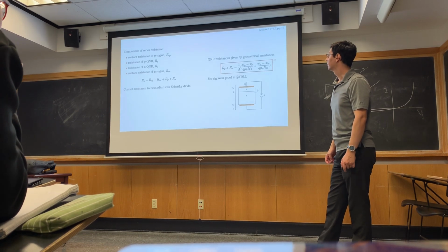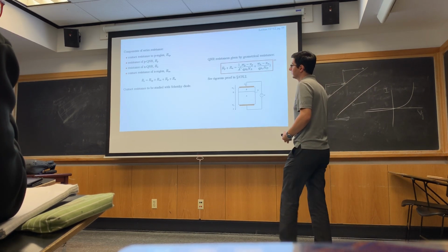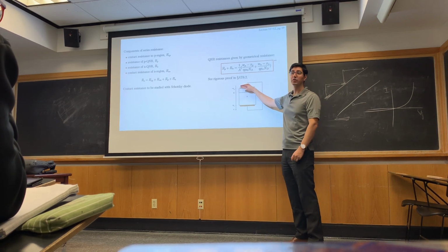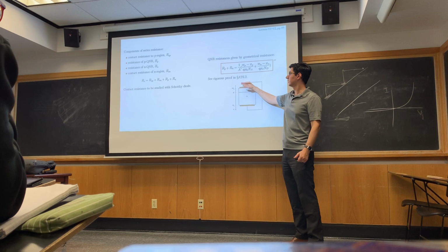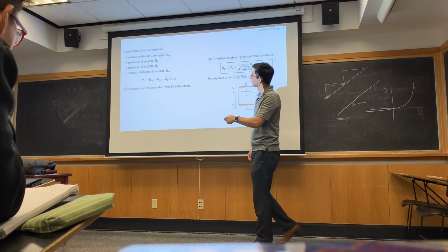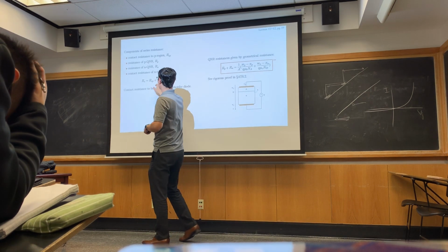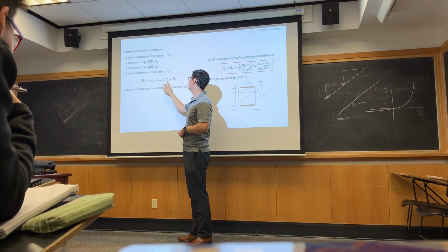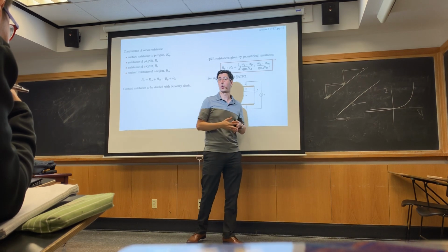Okay. And so we can be a little more rigorous with this and break that series resistance up into the contact resistance, top and bottom, and then into the resistances RCP and RCN, the contact resistances of the P and N side, and then RP and RN, which are just resistances of the quasi-neutral regions.